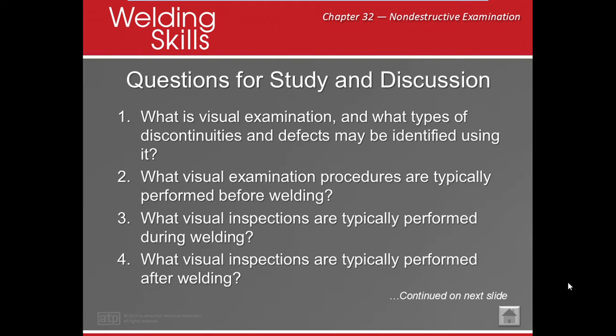What visual examination procedures are typically performed before welding? Prior to welding, we're going to review drawings and specifications, establish hold points, develop documentation, review any materials, examine the base materials, as well as fit up and any type of consumable requirements like your electrodes.